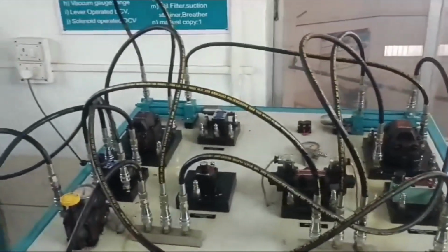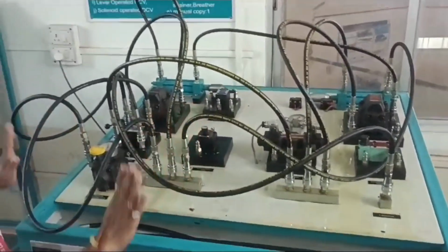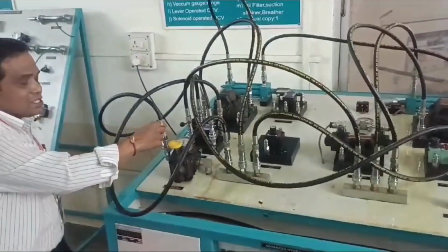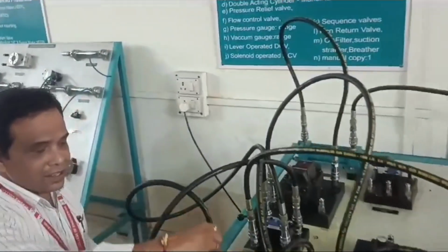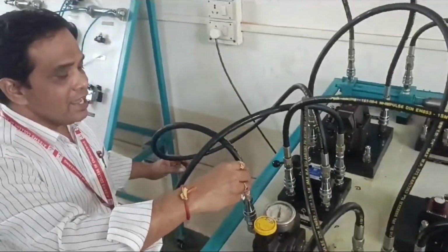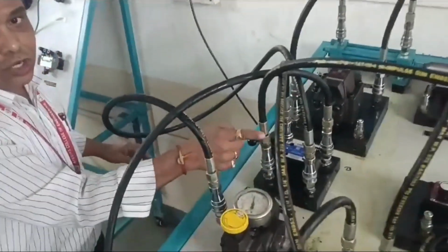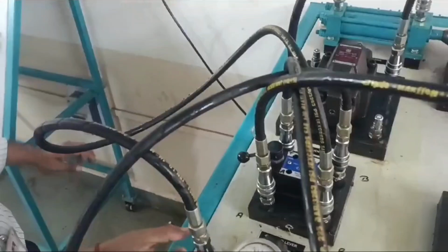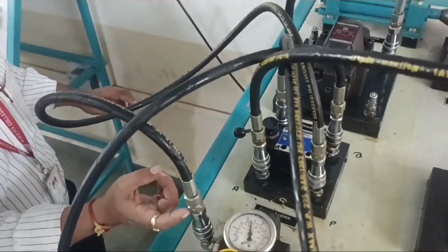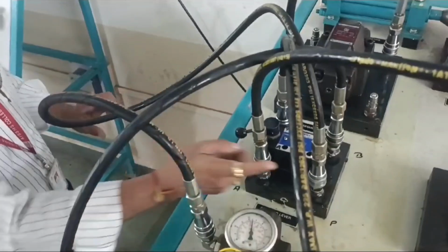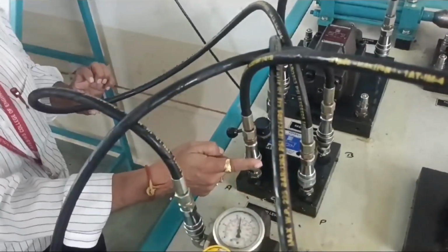Now you just see the circuit diagram of this sequencing circuit. This is the pressure relief valve. The pressure is coming to the pressure port P. This is the direction control valve, a 4x3 direction control valve. So this pressure port, this is the system pressure. This system pressure is connected to the P port of the direction control valve, and